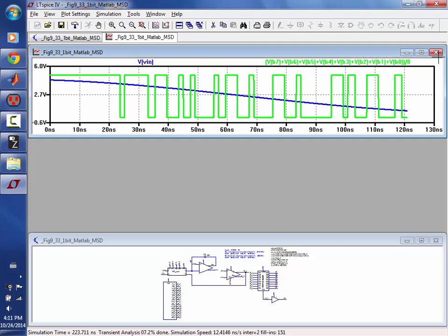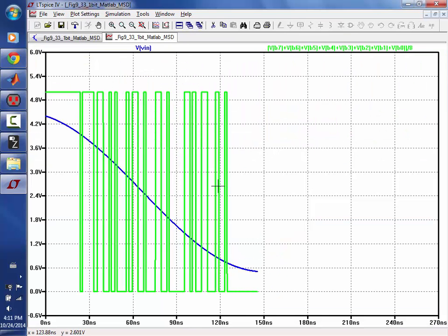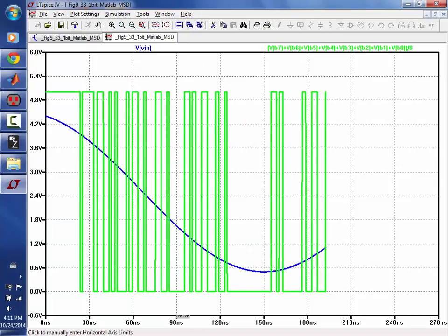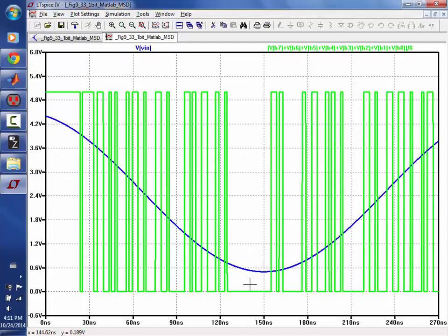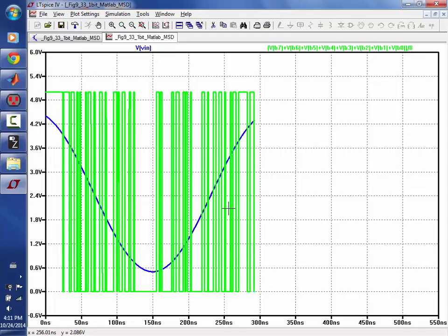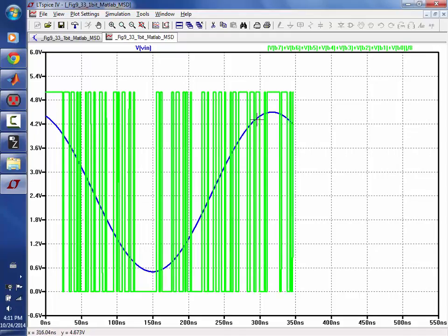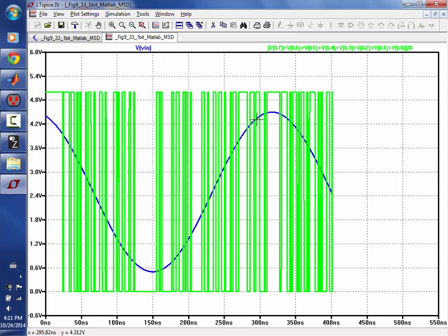Well, maybe it won't be on this machine. It was on my machine. But it works great to start out with. You see we're getting nice 0s and 1s, and it looks reasonable. Everybody looks at this and realizes, oh, it's low here. That's what we expect because it's a moving average of the analog input. Here it's high most of the time. That's what we expect, etc. But around 2 microseconds, it starts to die.